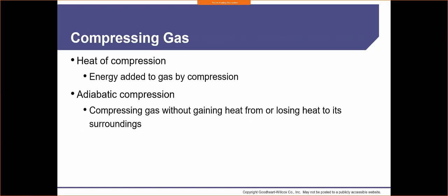So compressing gas, heat of compression. That's energy added to gas by compression. So what's going to happen is we have a piston or a cylinder compressor that's running. As we start to compress this gas, just by the physical force of the compression between the piston and the valve body or the valve head, you're going to start to generate heat, okay?